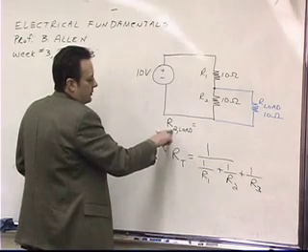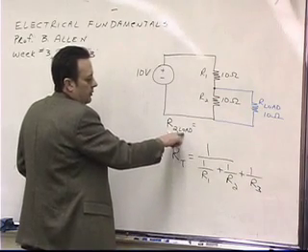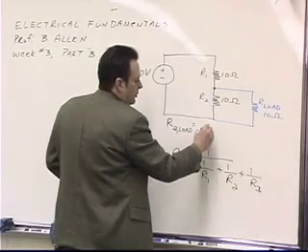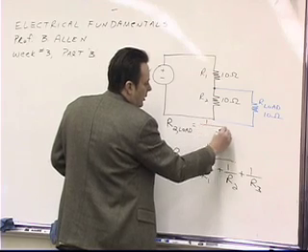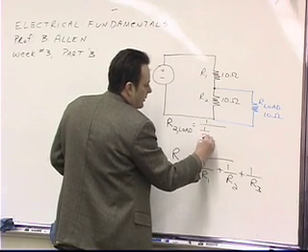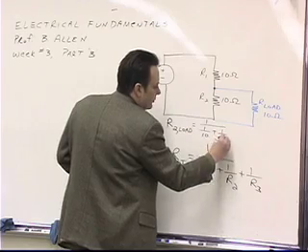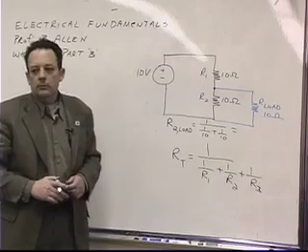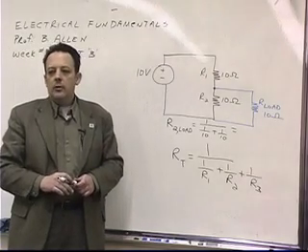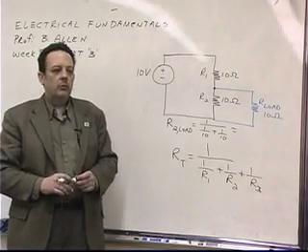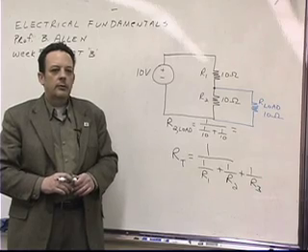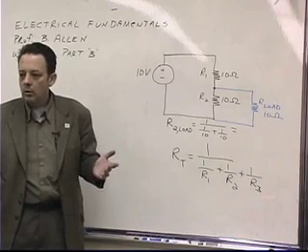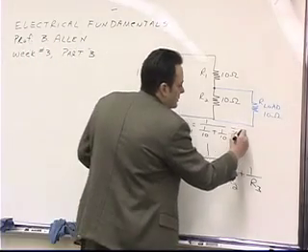So I'm saying that's resistor 2, load. Resistor 2, load is equal to 1 over the inverse of 10 plus the inverse of 10. If you get your calculator out, if you can't do that in your head, what is that? 5 ohms. It got smaller.